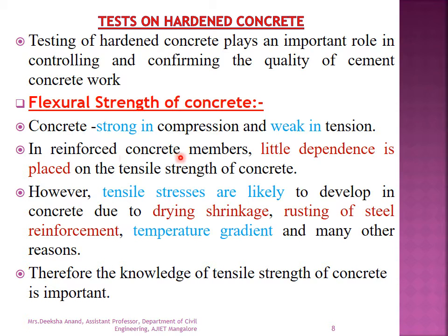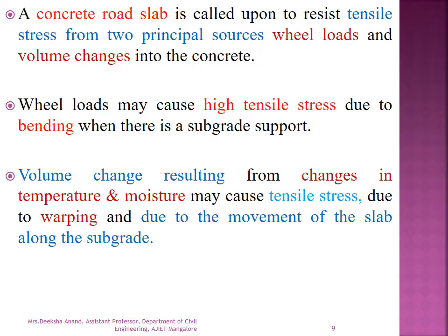So in a reinforced concrete member, little dependence is placed on the tensile strength of the concrete. However, tensile stresses are likely to develop in the concrete due to drying shrinkage, rusting of the steel reinforcement, temperature gradient, and many other reasons. Therefore, the knowledge of the tensile strength of the concrete is important.